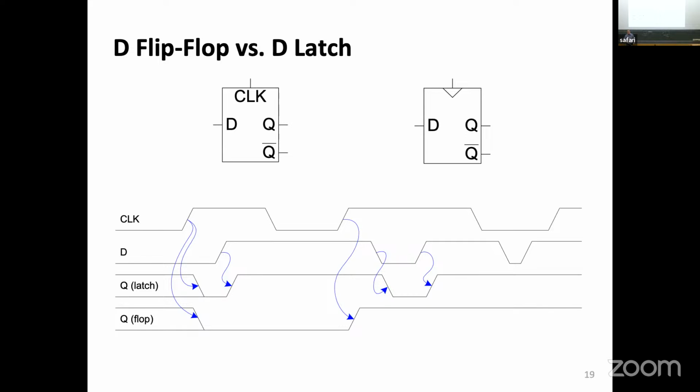If you remember in the latch, there were these 2 inverters. The signal has to propagate through and come out. So there is a bit of a delay, maybe even a bit more delay than what I showed, maybe there's something more secretive. And then the data stays like this. Now we are in the memorizing state. Nothing happens. And then here, I'm changing the input and the output changes directly after with some propagation delay.